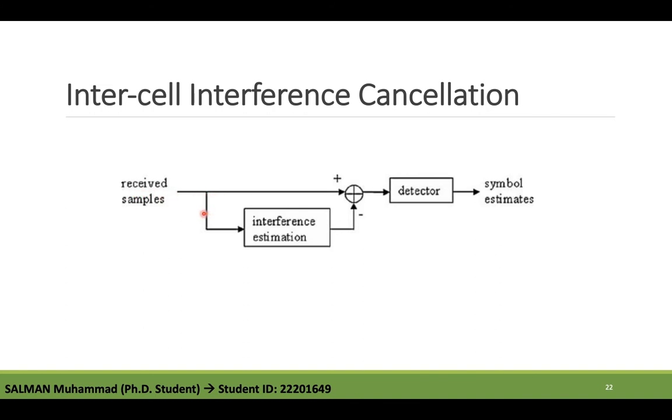The signal received from the base station is first estimated and then subtracted, due to the orthogonal spread of data symbols and the resulting redundancy in the transmission. MC-CDMA provides the possibility of iteratively removing the inter-cell interference at the receiver side without the need to perform highly complex channel decoding steps in the interference estimation loop. Therefore, MC-CDMA provides the means to perform the inter-cell interference cancellation at the price of a small amount of additional complexity. Basically, two approaches are proposed that differ in the way the inter-cell interference signal is estimated.